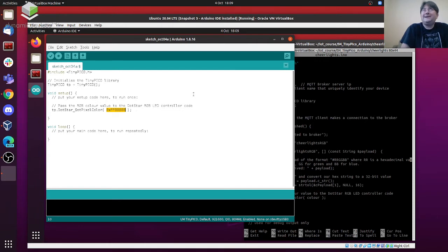That's a value in hexadecimal, or base 16. And we use base 16 quite a lot in computing because it makes it easier to see what the numbers mean for various reasons. If we split this up into 3 sections, there's an FF and a 00 and another 00. I've got one too many there. And the way we define this for our RGB LED is that the FF is the red color, and then the 00 is a green color, and the other 00 is a blue color.